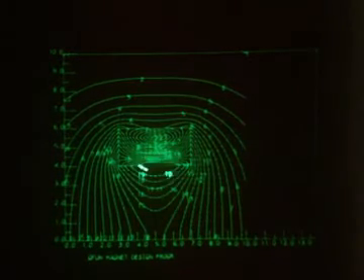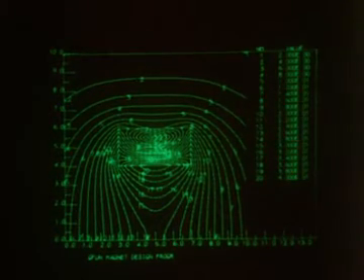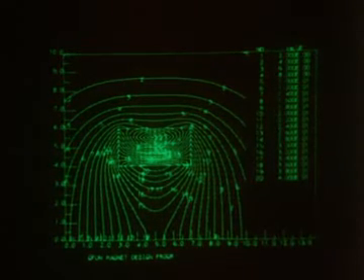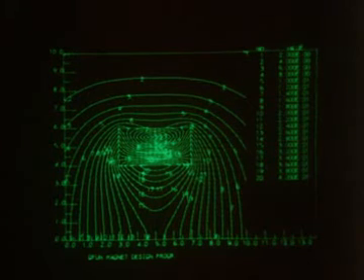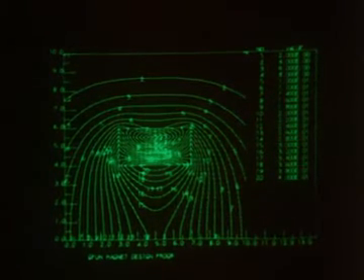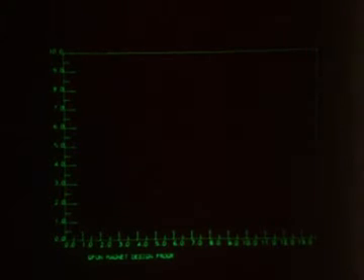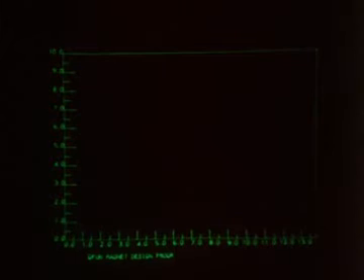For a more complex example, consider the design of a dipole magnet for one module of a superconducting accelerator. A crucial requirement of such a magnet is that the field in the aperture must be uniform to better than 2 parts in 10,000. Here the aperture radius is 5 centimeters, and the conductors are sector-shaped elements.